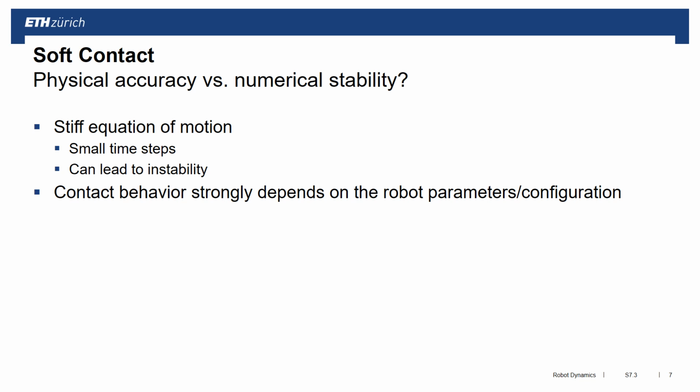So in other words, I always have to retune parameters depending on the robot, and also depending on the configuration of the robot. So if I'm colliding with a stretched leg, which means we have a very high inertia, obviously high inertia means that it can lead to large deflections if I have low stiffness, while if I am completely retracted, with a very low inertia, I have completely different inertial properties at the end effector and hence different spring mass damper oscillation behavior.